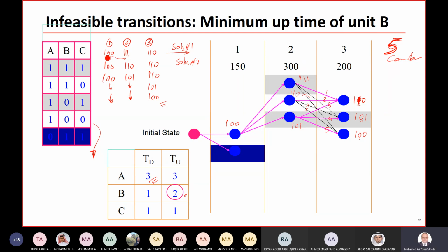You have the incremental cost lambda, and then you can calculate the cost at this operating pattern, and at this operating pattern. And you calculate the operating cost. This is the fuel cost, and we have different types of costs. We have fuel cost, and this comes from the cost function. And we have a startup cost, and this comes from moving from one combination to another.